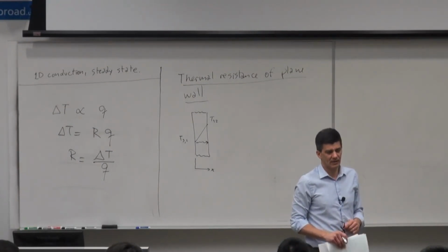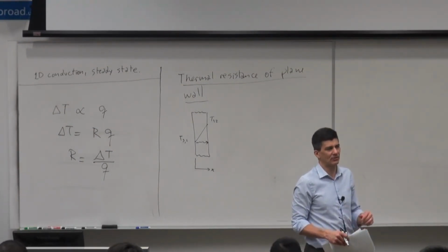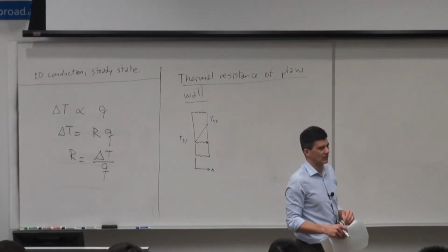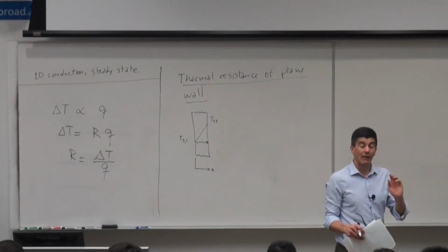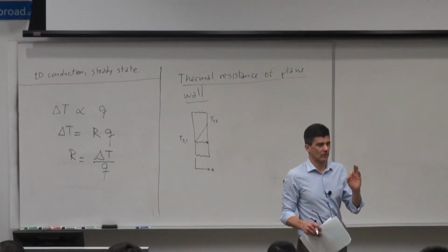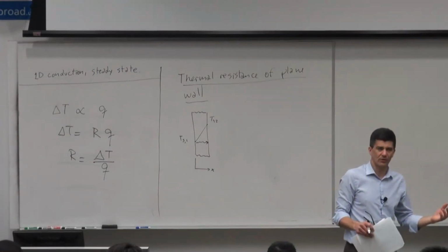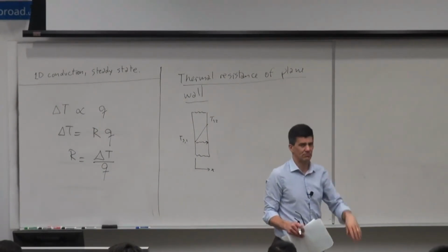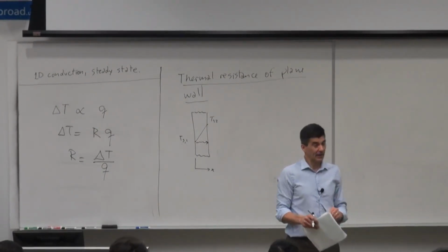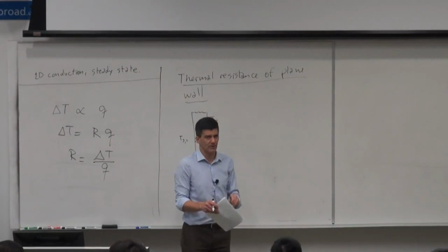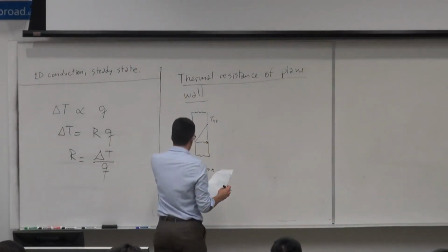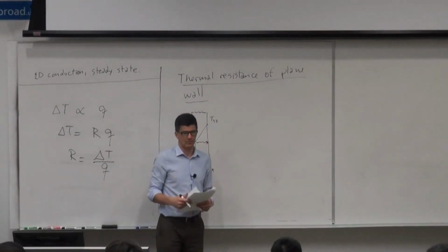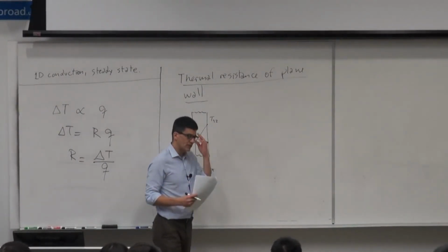Of course, you can have calcium fluoride, the special glasses that are transparent to radiation. I'm not going to worry about those exceptions. Liquids, like water, we're going to say is opaque to radiation. So yes, you can see through water, but the infrared radiation that brings heat, no, that doesn't go through the water. Air, yes, we're going to say air is totally transparent, or argon or helium or whatever. Anyway, so through this wall we can only have conduction. Can I have convection inside the wall?